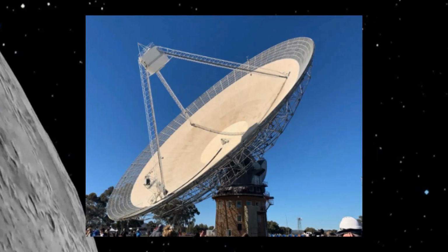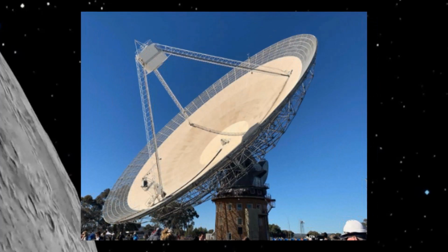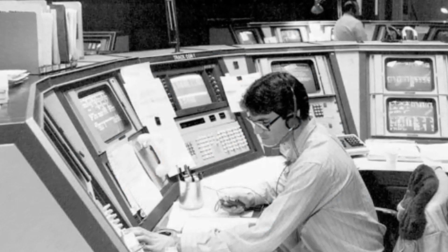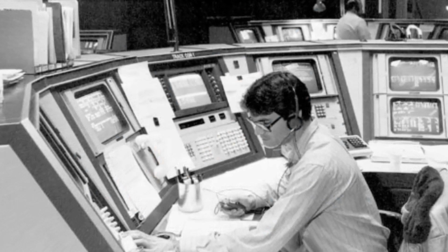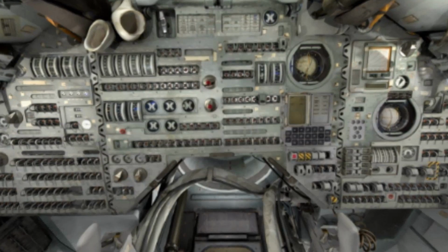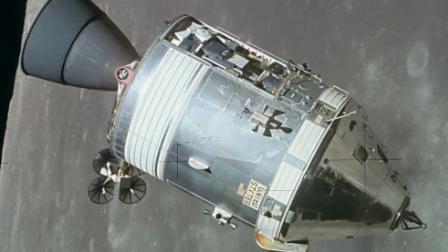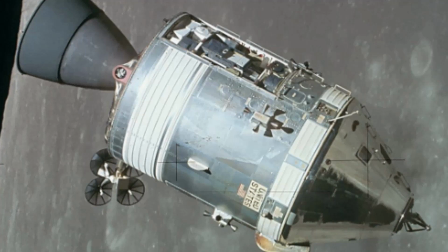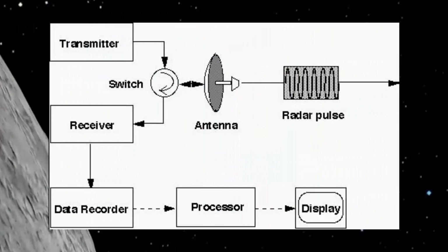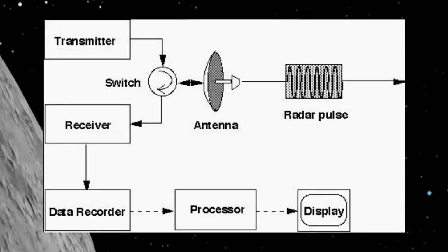Given that a powerful, accurate radio signal would in any case be sent to the spacecraft to carry voice and data from Mission Control, engineers simply arranged that it be modified on board in a known way and retransmitted back to the ground, this time carrying voice and data from the spacecraft. If the frequency of the signal from Earth was precisely known, then so was the spacecraft, if it were not moving. After equipment on the ground received a downlink from the spacecraft, the precise frequency was compared to the uplink.